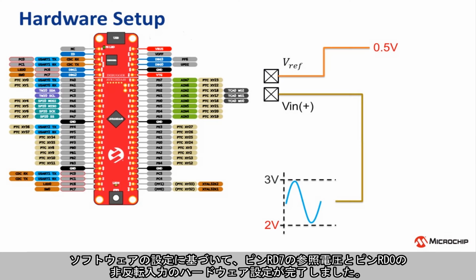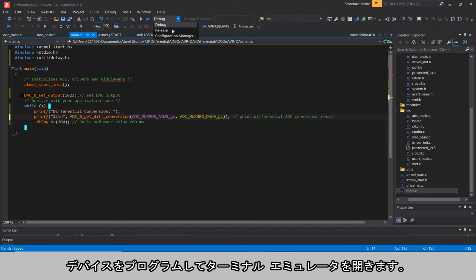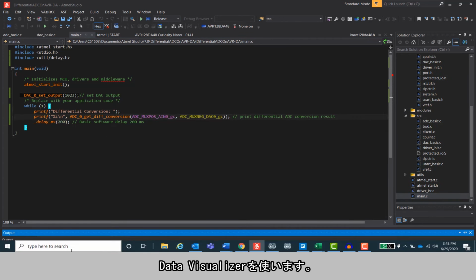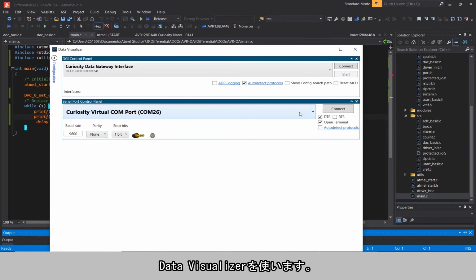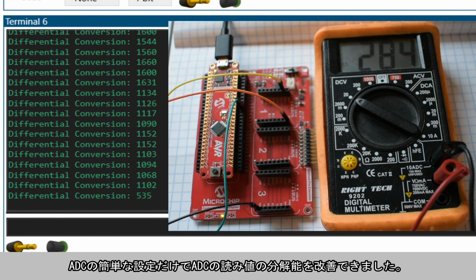Based on the software configuration, this is the hardware setup with the voltage reference on pin RD7 and positive input on pin RD0. So go ahead and program the device and open up a terminal emulator. I use Data Visualizer. And there we go. So there you have it. We just improved the resolution of our ADC reading with some simple configurations of the ADC.